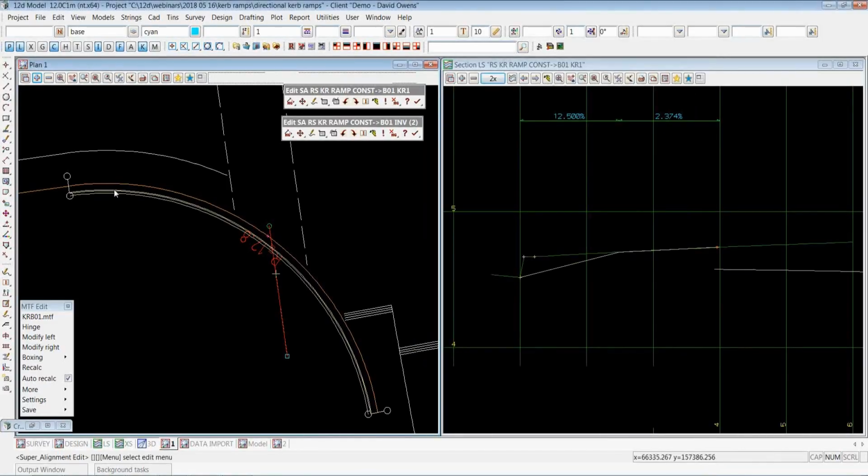So really tight intervals is the key on that one. Probably could have even gone even smaller, but this seems to work okay around that point. You notice there's a few other parallel strings in here, so I've just replicated the top of curb and back of curb. They might come in handy later on. So while I was there, I just created all three of them basically.